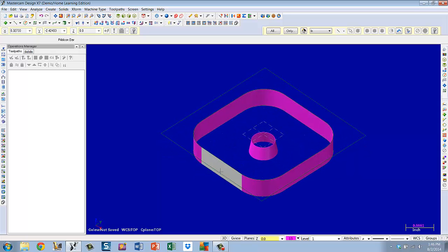Next, we're instructed to create the edge curve on the edge of the draft surfaces. We have two draft surfaces, but this one's actually got geometry around it at the bottom, so it's got an edge. We just need an edge for this boss. Our geometry is at the top, but we don't have an edge at the bottom, and we're going to need that to put our flat surfaces in so we have something to select in terms of a boundary.